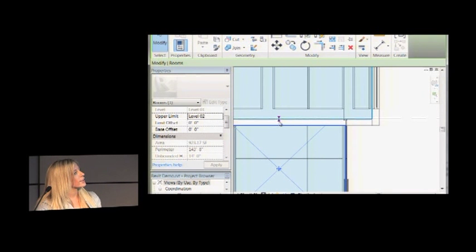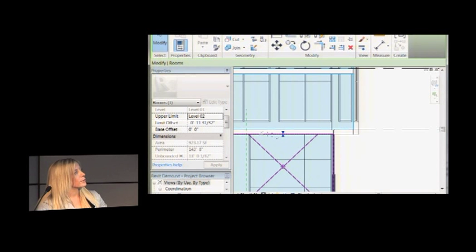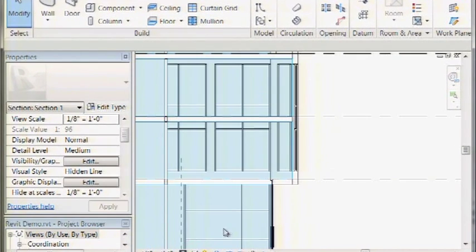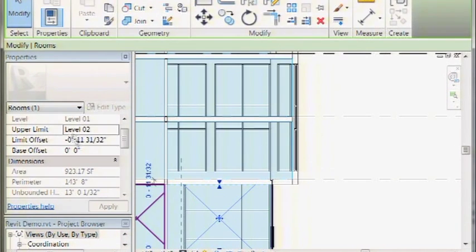That means that if I had tied this room height to here, it would actually think it's ending here, it's not intersecting a floor, and there's a hole on top of this space. So I have to tell it by saying this is actually tied to the height above, by tying it to a level. So it's, in a way, a little weird like that.